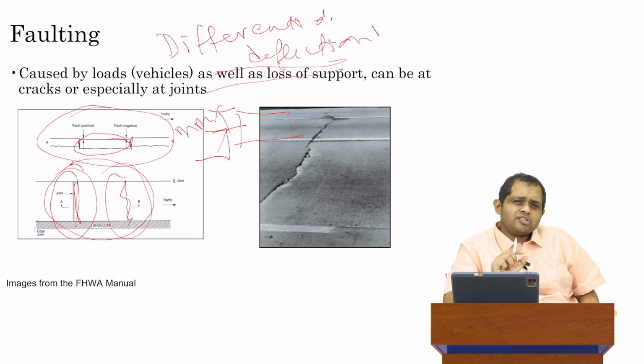So something as small as a 0.1 mm faulting can be extremely uncomfortable to a driver. And secondly, even that tiny amount of faulting actually puts quite a lot of strain on the suspension of the vehicle. So if you drive over a long distance over a highway which consists of rigid pavements with a lot of faulting, you probably will have to take your vehicle to a mechanic in the end, because some amount of damage is going to happen to it.